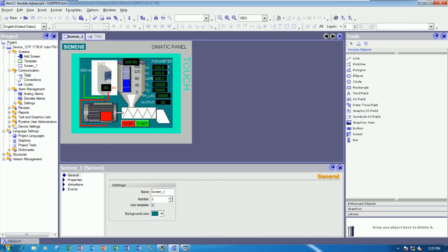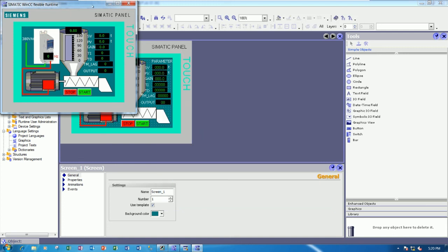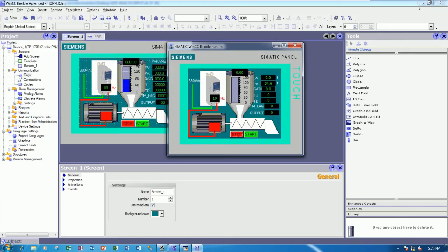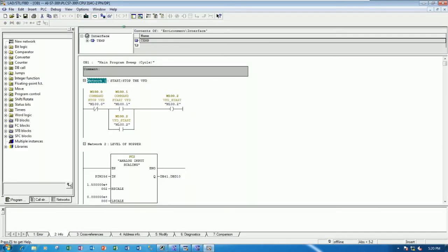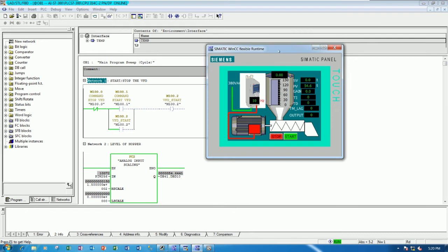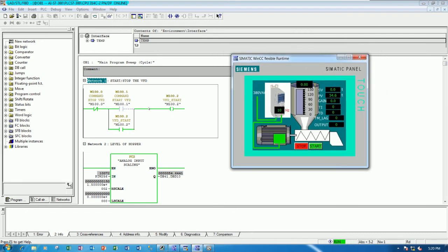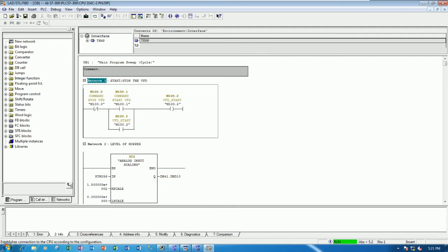and then we can put this one, yes, for start and stop is the same, right? So let me simulation, yes. Okay, so let's open the OB1 and then online. So let me check the existing program can use or not. So start, okay, it work. Stop, it stop. Okay, so the next step we need to create the output, right? It means that create the analog output scaling for control from the output the PID to the VFD, right? Okay, so let's start to create.